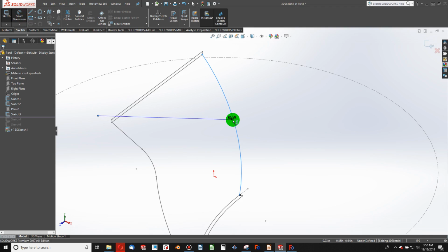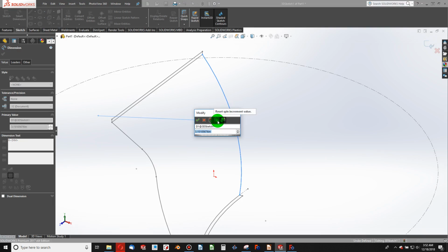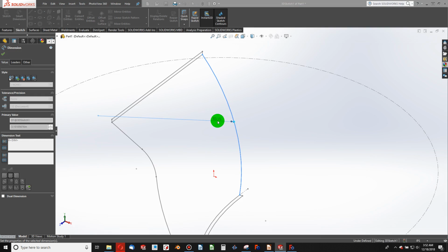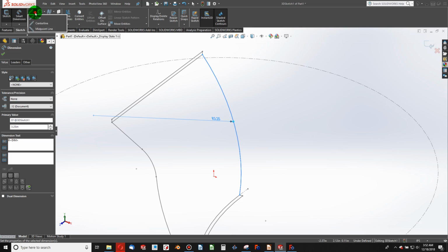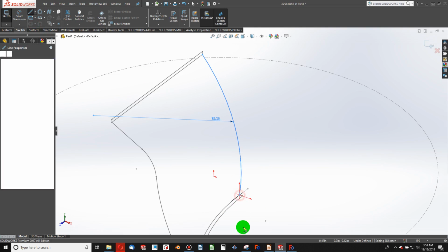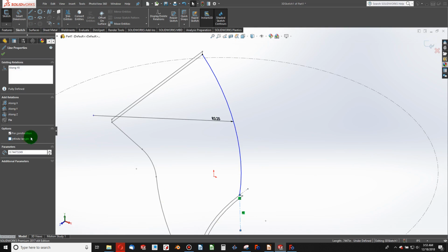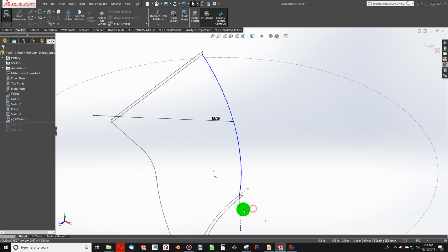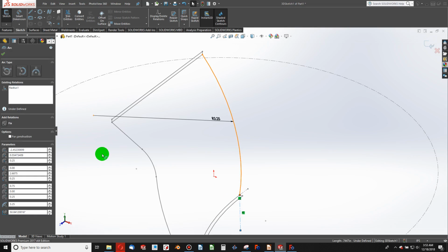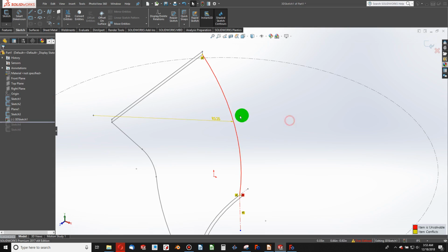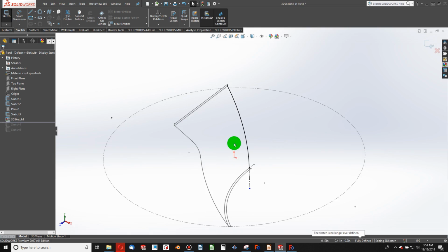I'm going to simply give this point to point and a radius, say a radius of 3.25, and then I'll give this a center line, and I'll make this go along my y-axis and make this tangent. Oh, and that interferes with my radius. Oh, okay, we're fully constrained. Of course, 2 points in tangency.